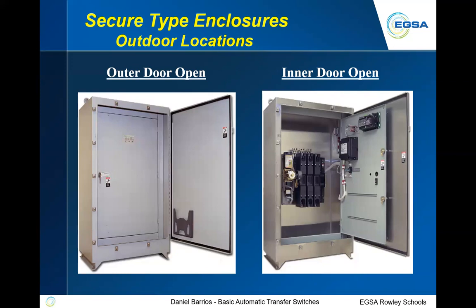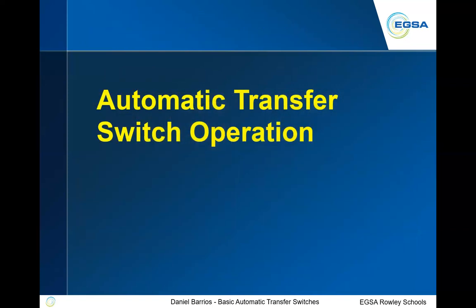And those can be either 304 or 316 stainless. Why? Many of these go onto the Mississippi Gulf Coast, possibly out in your area also, and the salt conditions just absolutely destroy a painted steel enclosure. Very expensive, but for the purpose, water treatment plants, anywhere that has caustic fumes, typically we will see an installation of a stainless steel enclosure.